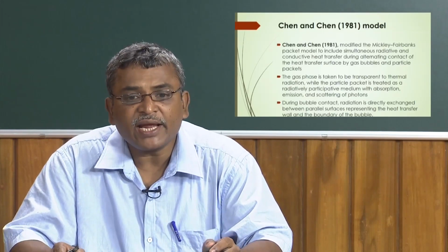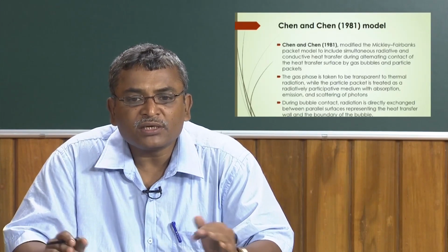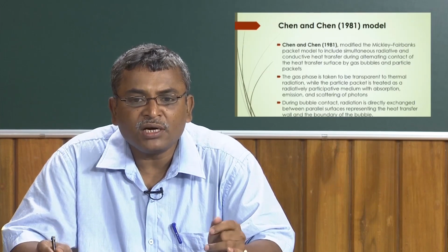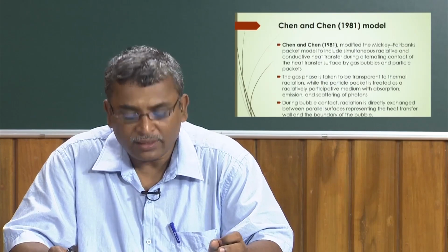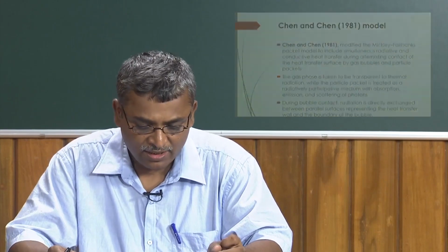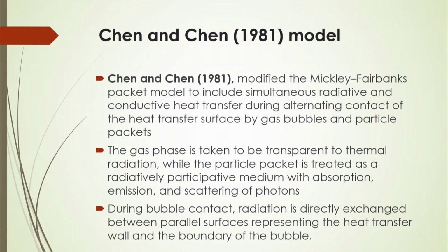The gas phase is taken to be transparent to thermal radiation, while the particle packet is treated as a radiatively participative medium with absorption, emission and scattering of photons. During bubble contact, the radiation is directly exchanged between parallel surfaces representing the radiant heat transfer wall and the boundary of the bubble.